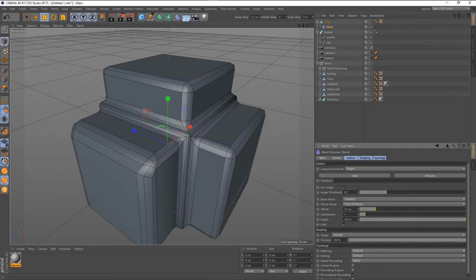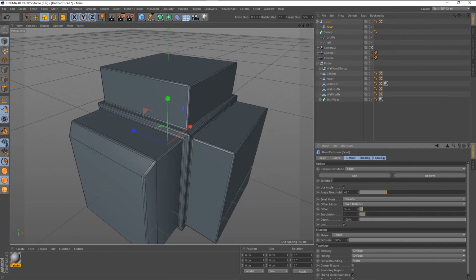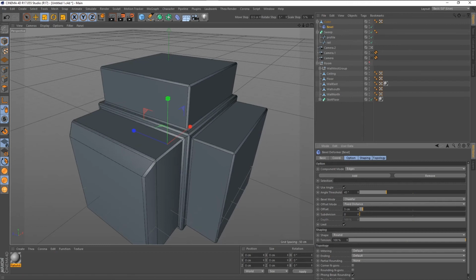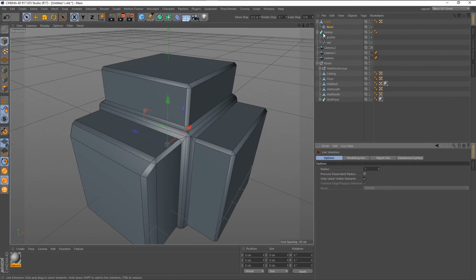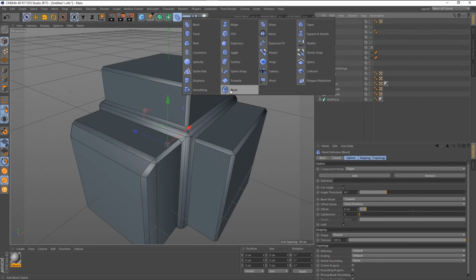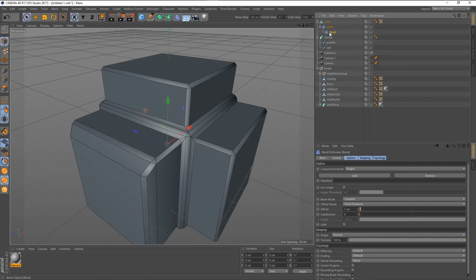Anyway, let's try this. Set this back to here, and then I can set a bevel on a bevel, which I want to do. So I'm going to set the subdivisions down to 0. Put this at 6, and now I'm going to choose the bevel, hold Shift down and hit bevel again. And on this bevel, use angle.